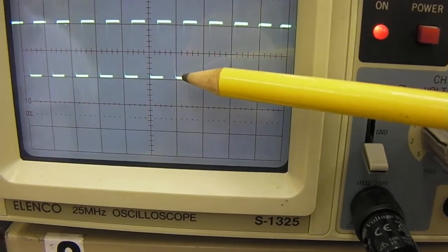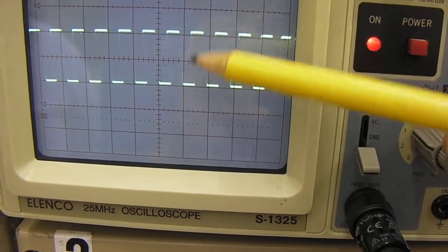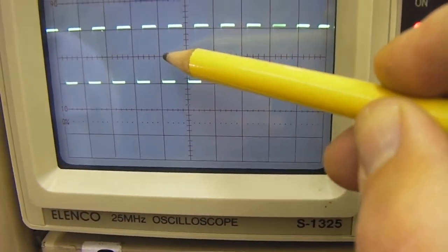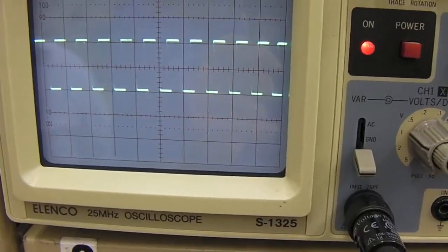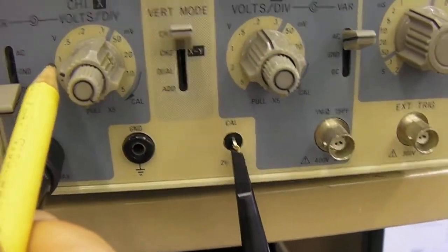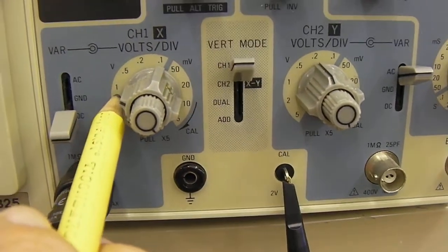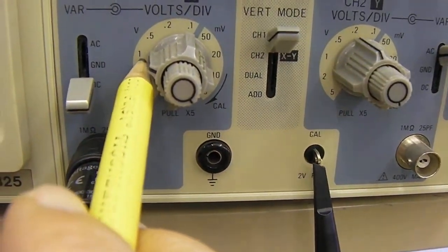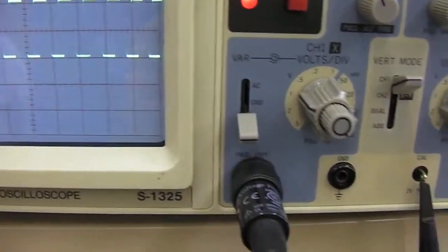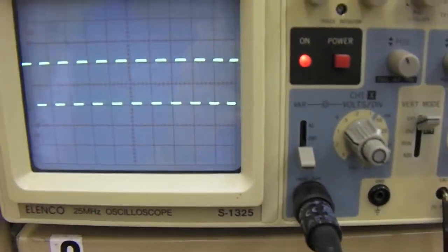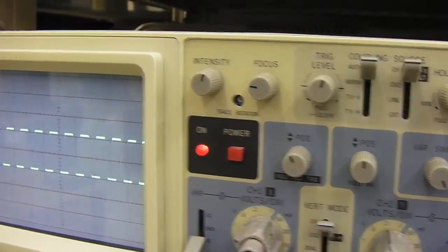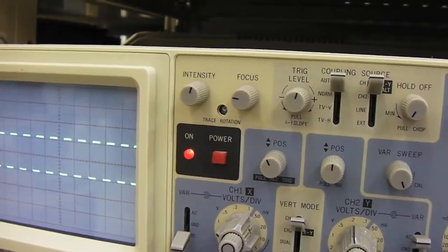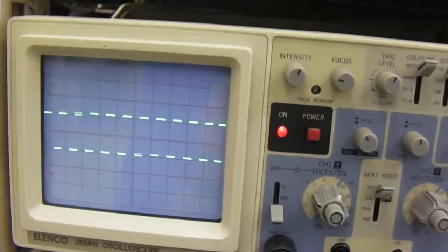So we have going up, that's volts. Volts is up and down, that's the vertical. So we go 1, 2. So that's just exactly 2. And then we'd multiply that by the volts per division here, and that would be 1 volt times 2. So what would that be then? 2 volts. Yeah, that would be 2 volts. All right.